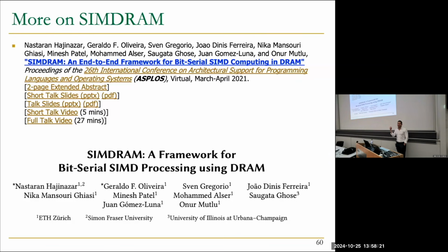So this BBOP instruction is treated as any other load instruction. It's registered in the MSHR entry, goes to the memory hierarchy, and eventually needs to go back to the CPU as well. So if the CPU is going to depend on that particular BBOP instruction, it's as if it's depending on a load. It's waiting for it to move back, basically. So in that sense, this is not asynchronous to the CPU.